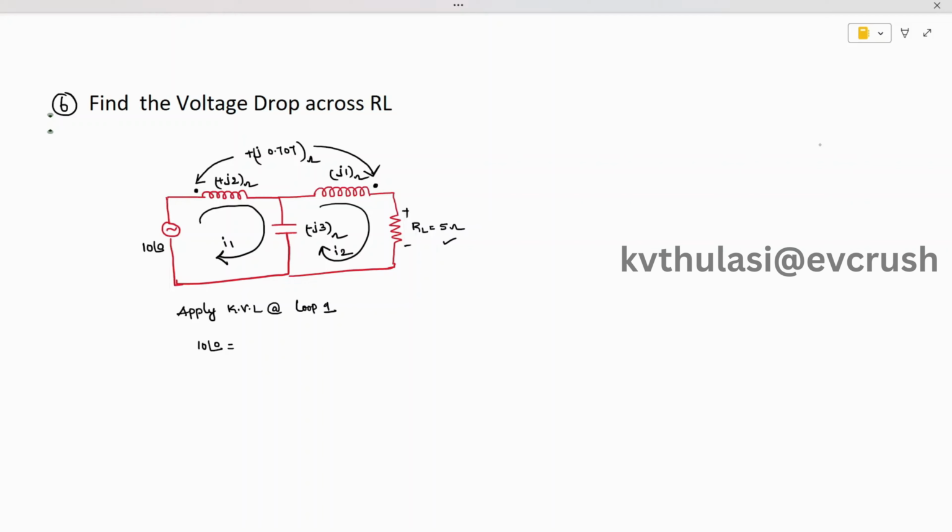Okay, so here, generally you can write the inductor in Henry, or you can write it in AC format as plus j XL ohms. So plus j XL ohms we can write as plus j into XL, and XL can be written as omega L ohms. So this is what is directly given here. It is plus j into 1 into L value given is 2 ohm, which is nothing but j2 ohm. So j2 is nothing but directly the XL value, which is 2 ohm. Okay, that's what is given in the problem.